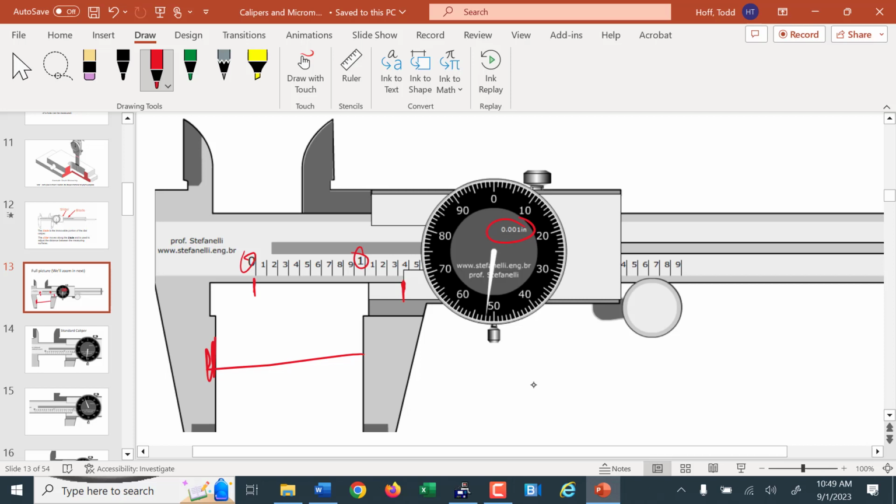How many of you have read standard calipers before? Good, so we can get through this relatively quickly. So on the main scale, you get two numbers, whole inches and tenths. So on the main scale, how many whole inches do we have? 1. How many tenths? 3. Perfect. So it's 1.3, and then on the dial, that lines up with 52. So 1.352 inches is what that's reading.